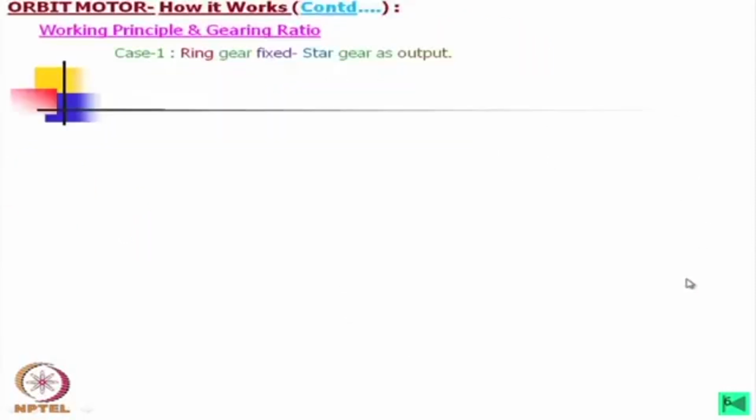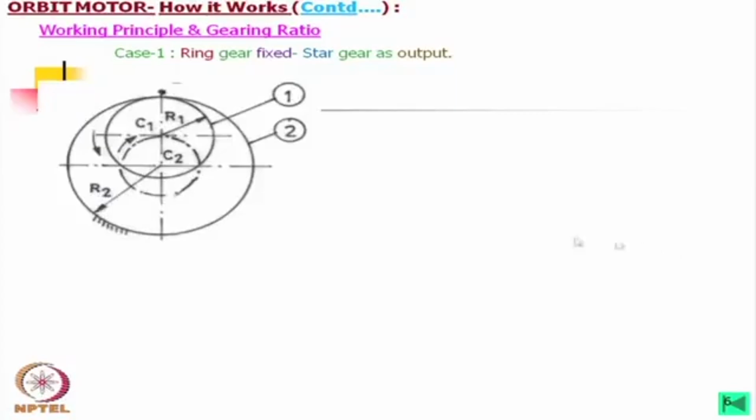Okay. Now, let us see this working principle. The first case we shall study is the ring gear fixed, star gear as input. Now, these two circles, we should call base circles if it is in terms of involute teeth. If it is of other teeth, say cycloidal teeth, usually this is called the describing circle.